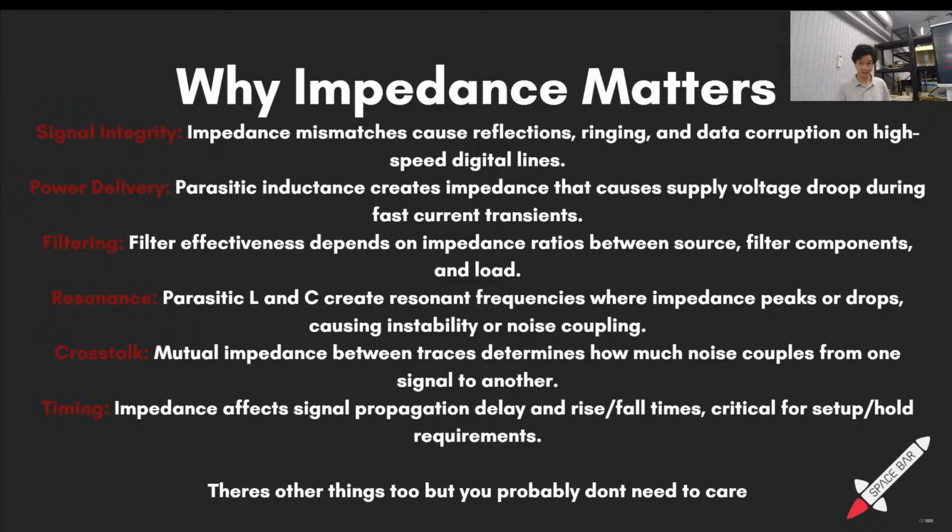But basically, you have resistance on the x-axis, and then you have reactance on the y-axis. Reactance is summing up inductance and capacitance in some way. Then you take the hypotenuse of those two and you get the magnitude of your impedance. And then you have the angle between the hypotenuse and the x-axis, right?